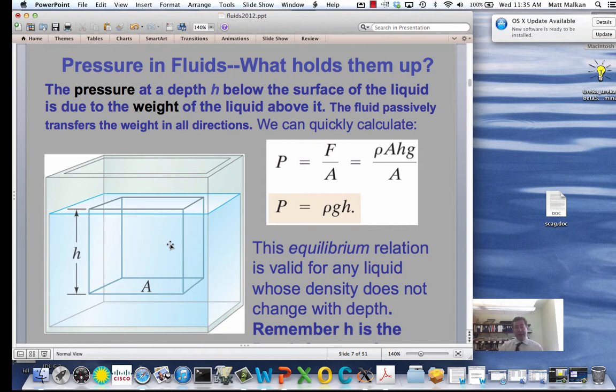And we know that that has a certain amount of mass, so it must have a certain amount of gravity acting on it, M times g. It's a certain mass which we'll be able to figure out very easily. That's just the volume times the density of this material, rho times A times h. We multiply it times g. There's your force of gravity. And this gravitational force is pulling it straight down, and it must be exactly balanced by some other force that's pushing it straight up. What is the other force?